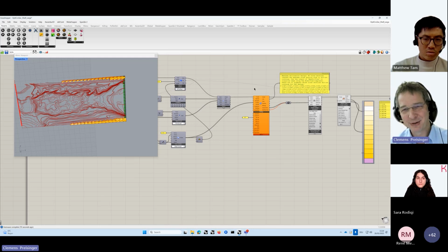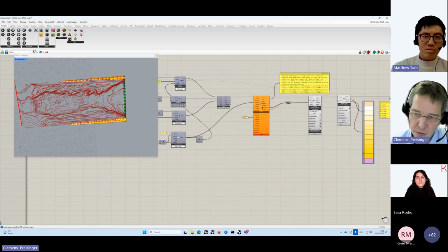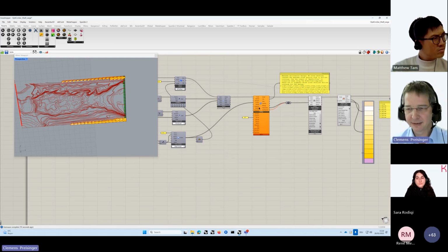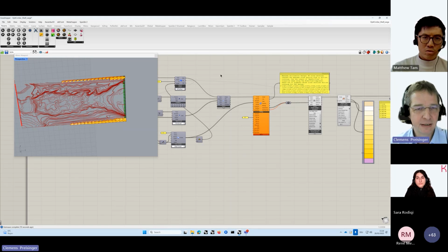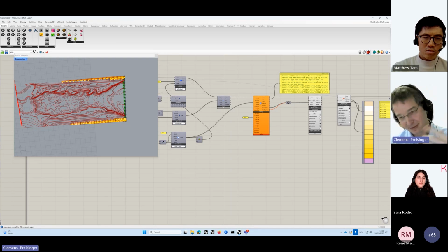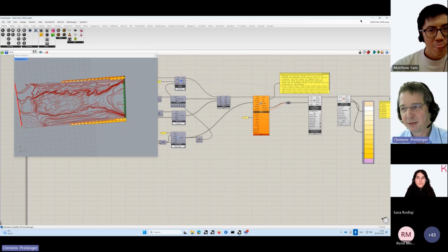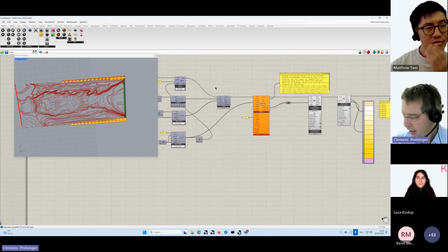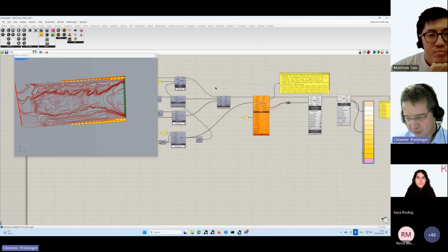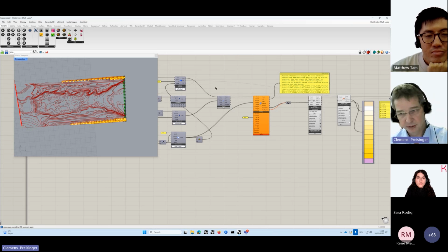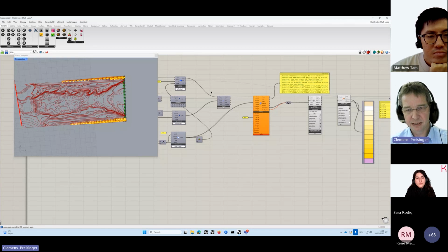So unless you are doing a presentation with Teams, the components work in the background, and your progress isn't impeded by the calculation. However, one thing, also besides the fact that it's not compatible with Teams, is that in case of optimization with Galapagos, for example, or doing loops, one needs to disable this option, because otherwise it crashes Galapagos.